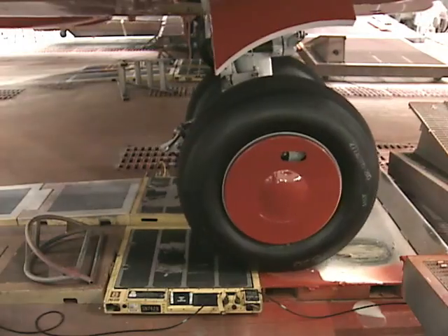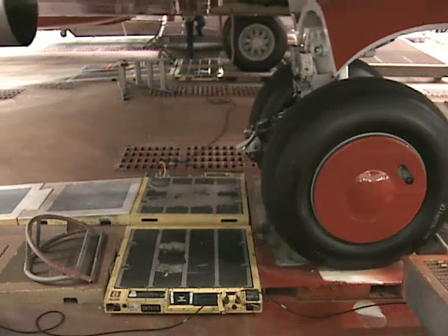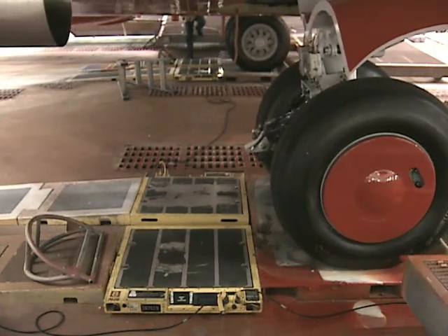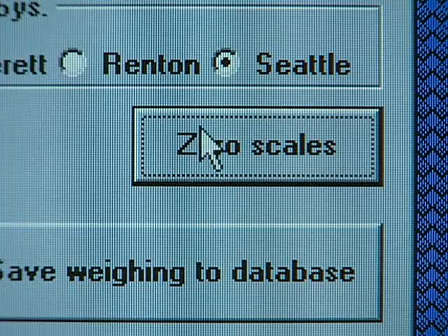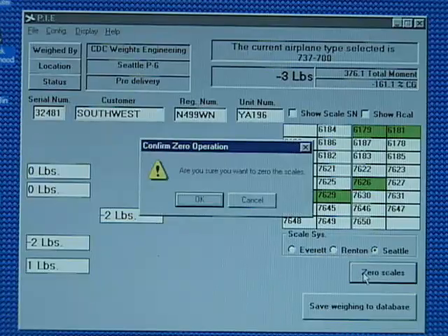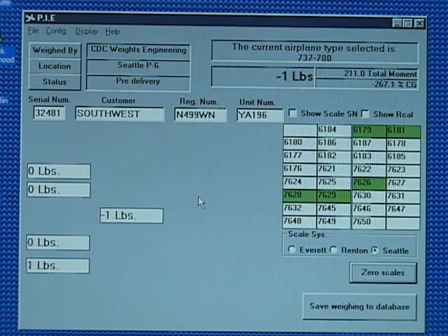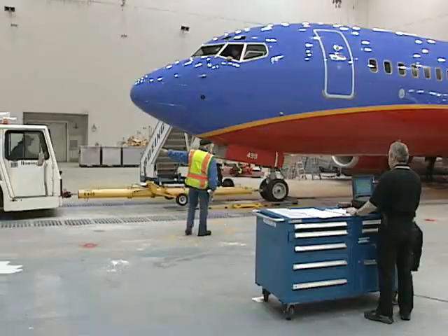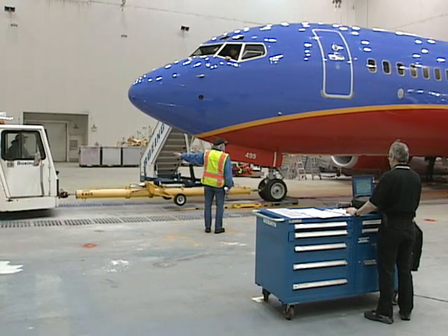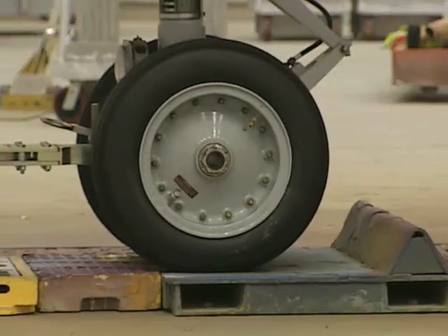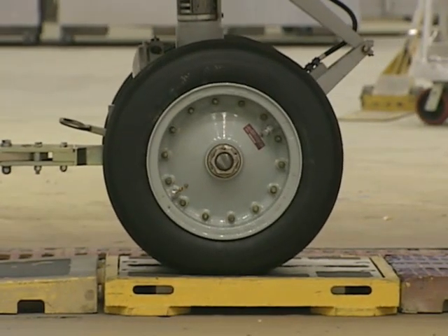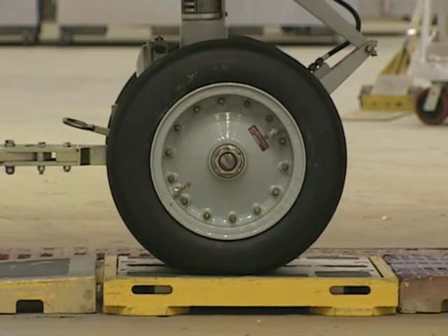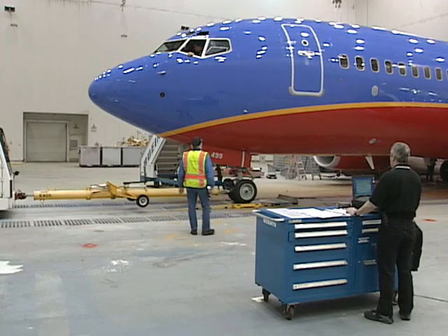You should exercise the scale by temporarily turning the airplane onto the scales. This makes sure that your platforms are operating freely, giving accurate readings. If at this point or at any point in the process the scales show readings that you suspect are inaccurate, investigate and take corrective actions. This could mean replacing defective or out of calibration scales.